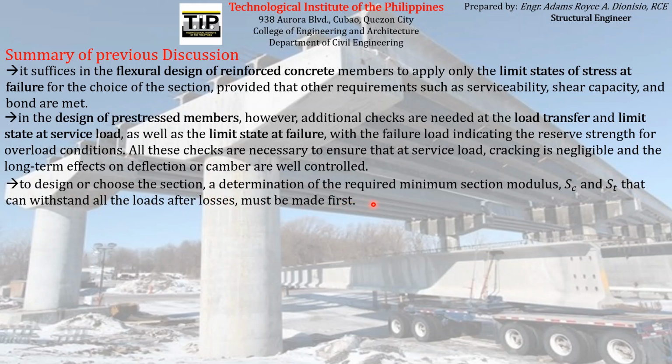So when we conduct service load design for a pre-stressed concrete member, we usually first check the properties of a particular section that is compliant to the minimum section modulus SC and ST that came from the stresses from the applied loads that are supposed to be carried by the pre-stressed concrete member that we are designing.